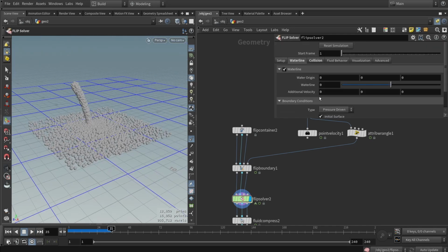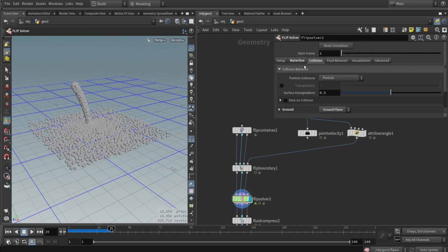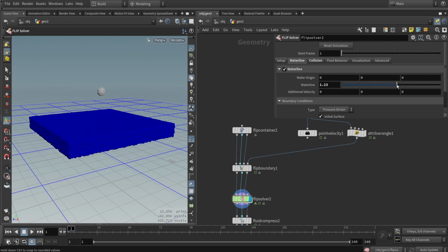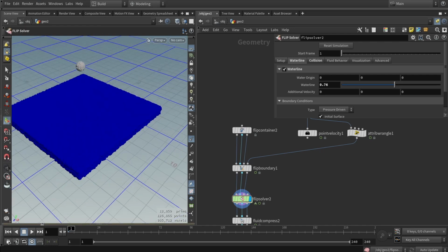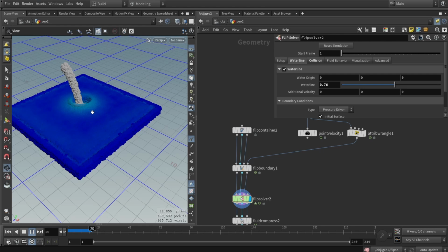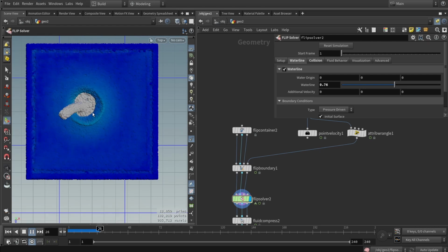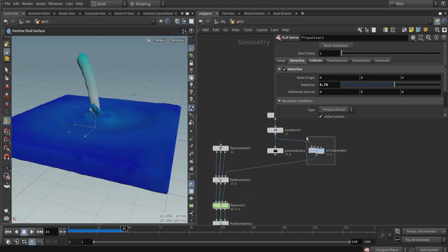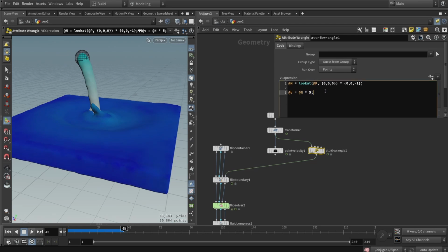And because I now also have a ground layer or a ground plane, my waterline needs to be actually also higher. So we can actually see the waterline like this. So let's play this again. So we now have the proper simulation as I expect. So I'm going to quickly view top here. And as I said, it will always be aimed towards roughly that middle point, the look at direction. So this is just interesting to know that we can use normals or create our own velocity attributes just by code with VEX or something like that.